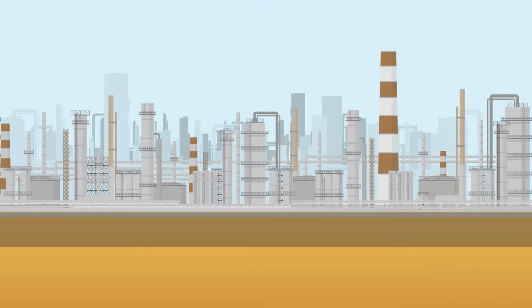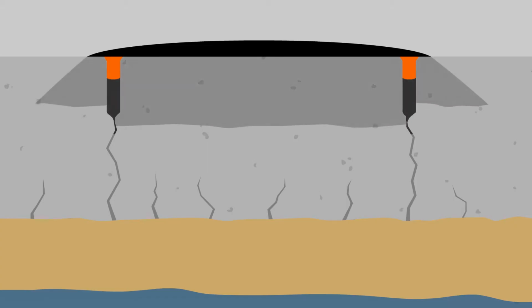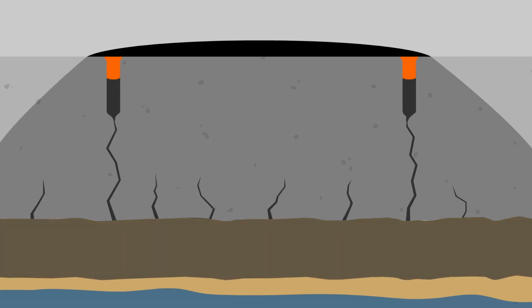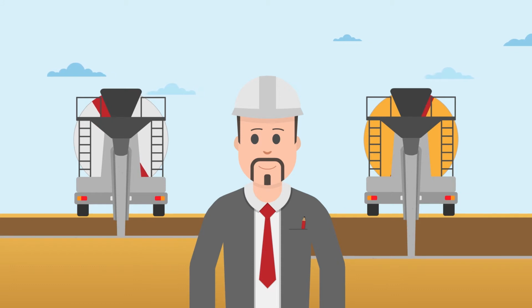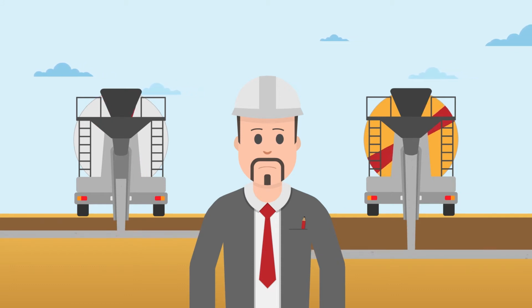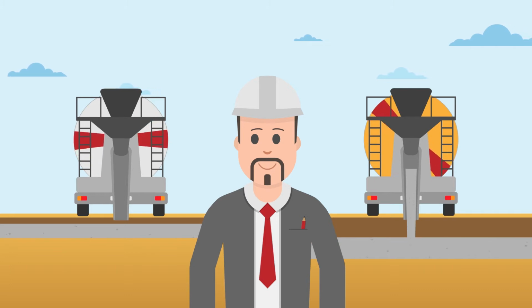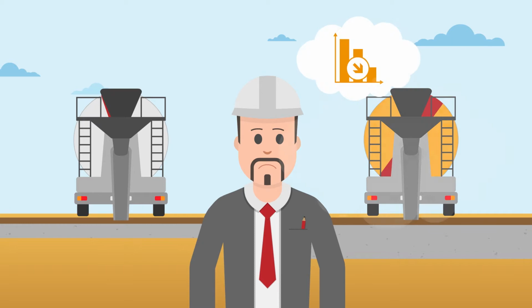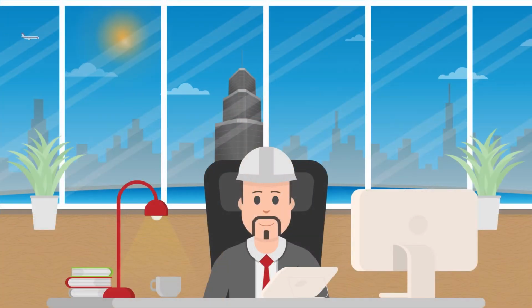They state that substances hazardous to water are not allowed to penetrate deep enough to reach cracked areas, even after up to 144 hours. This is why planning often involves doubling the building component thickness. In the case of Tom's basin, this would mean that the concrete would be 50 centimeters thick instead of 25, which would be inefficient and very cost-intensive. Tom wants to avoid this.